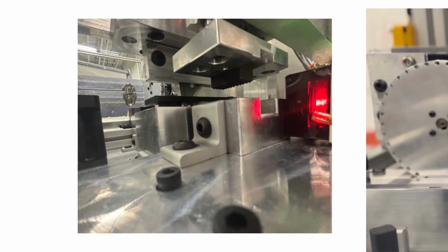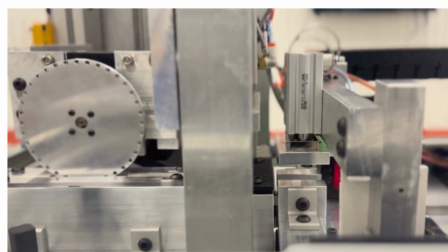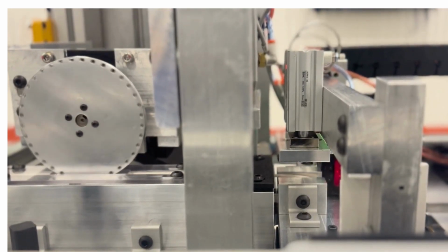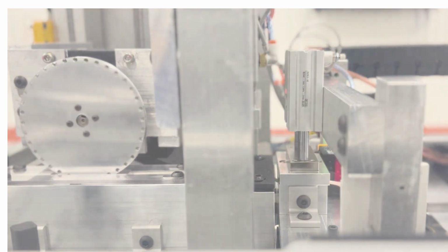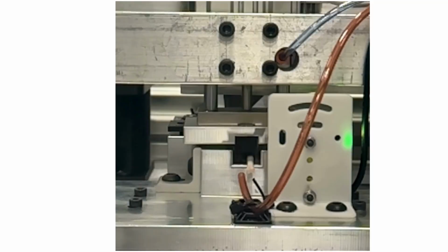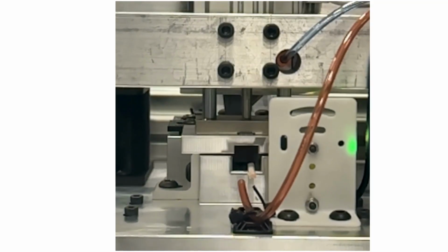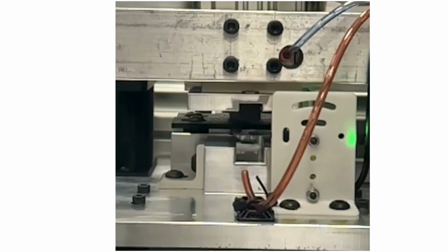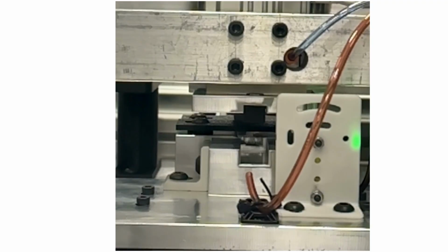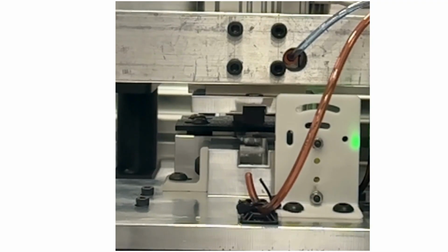Gripping and tensioning. An AC motor feeds the thread through the spring guillotine clearance block until it enters the gripping mechanism. A beam break proximity sensor detects the leading edge of the thread and immediately halts the in-feed motor. A pneumatic cylinder clamps down with the flat surface grippers. Flat grippers were selected over a tooth design during prototyping to eliminate material accordioning and keep the thread completely straight.